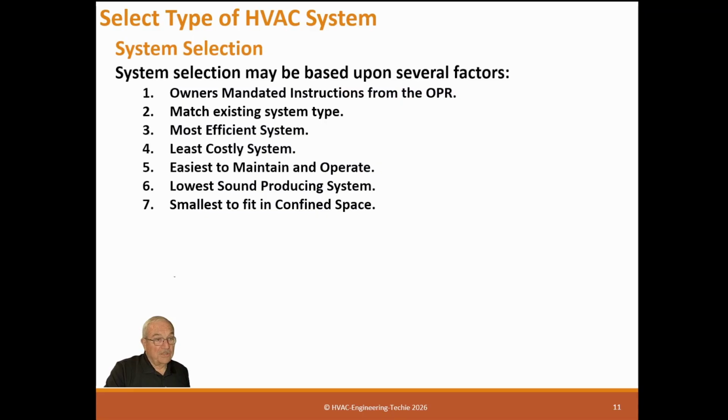And that's why you as a designer need to coordinate with the architect, because the architect never gives you enough room, ever. Or they almost never put it in the right place. So if you can get in early at that 35% and state your case of why you need this, especially if money's a problem or efficiency's a problem, then where they put things actually matters. If you put a fan room way down the end of the building, it's going to cost more to build, and it's going to cost more to operate. And sometimes architects don't understand that, so you need to help them with that.